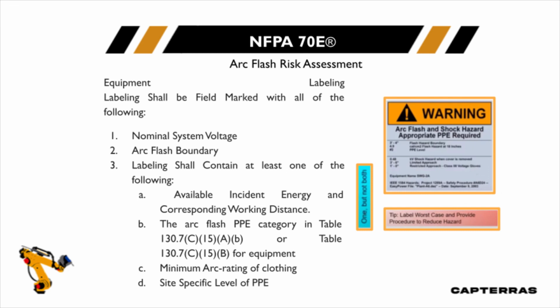What if I'm in a transfer switch that has line isolation bypass and a bunch of busing, and the ARC spreads to both sides? So maybe our calculated value with worst case on one bus is 30 cal, but if it spreads to both buses, and now the generator and let's say the utility source are present, and they both get involved with the ARC, what is your exposure there?